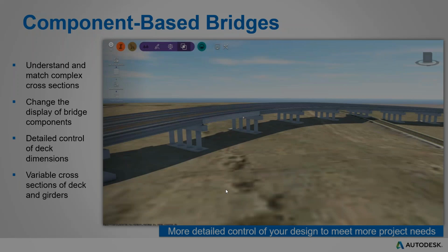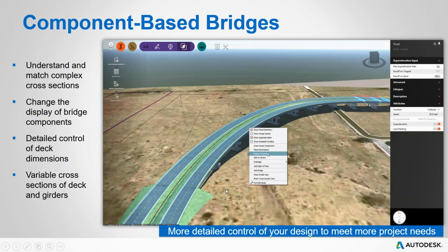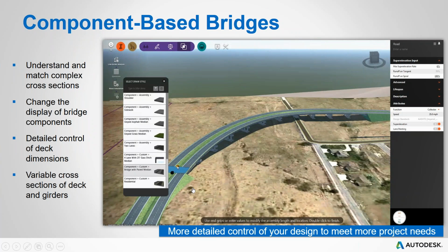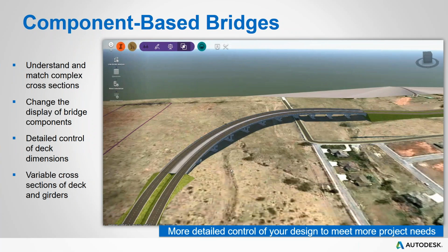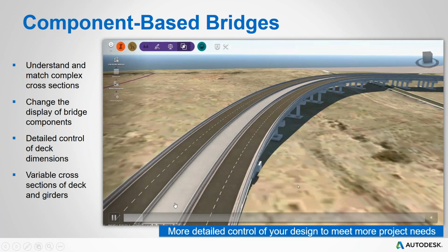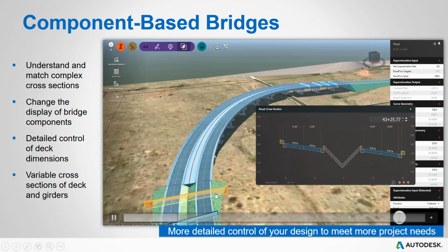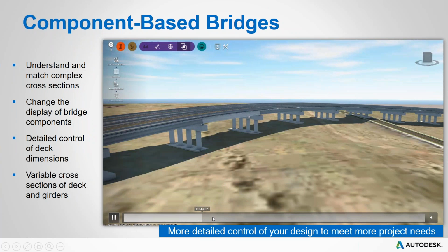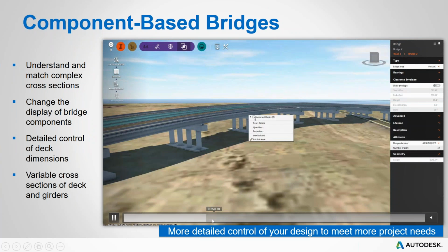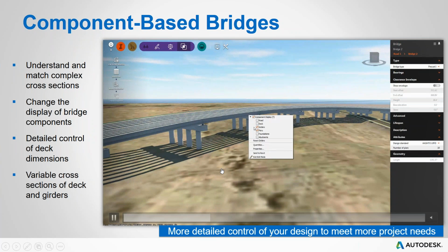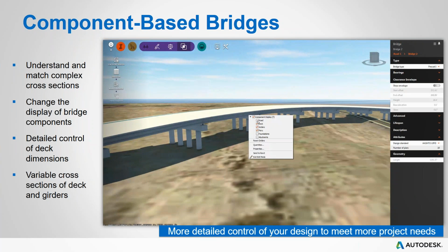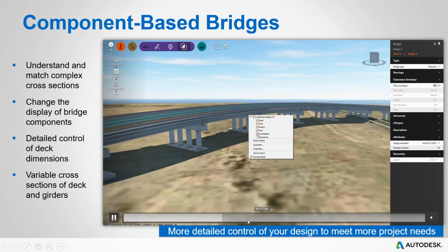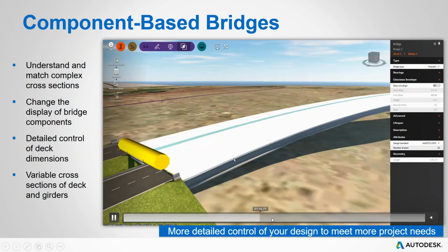What's really important is that all of these components can be modified individually or as groups. So you can change the style of the road on top of the bridge. You can create different zones. For example, you can also check the cross section along that bridge. Some of the built-in analysis tools within Infraworks let you pick a certain girder and select which structural objects you would like to see, so that you see some of them and not others, simplifying the analysis and visualization process.